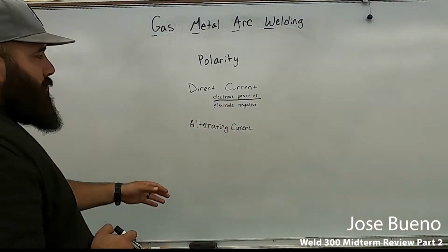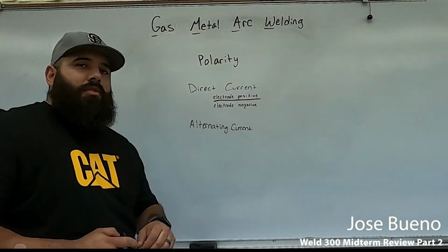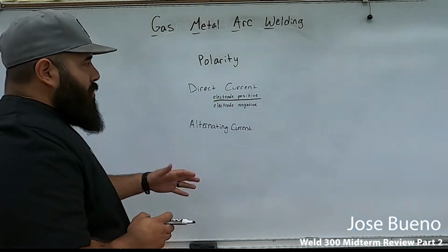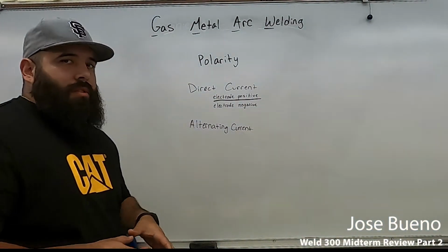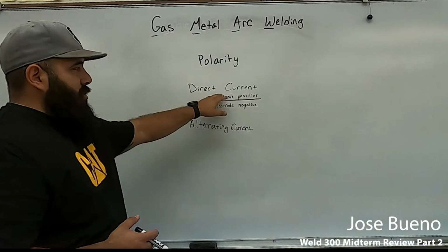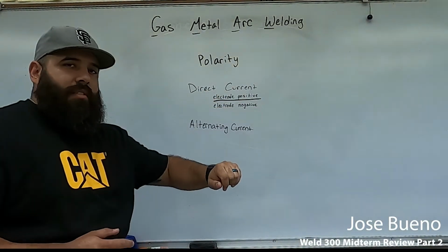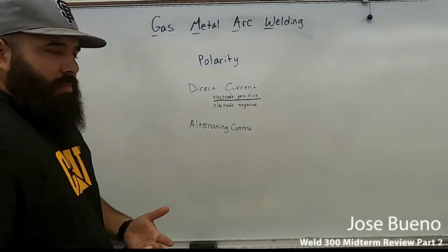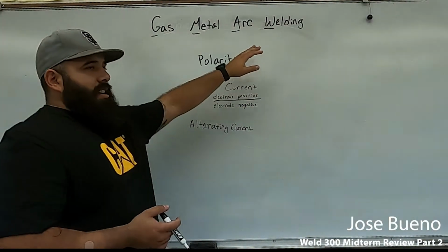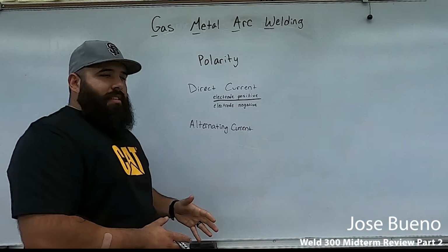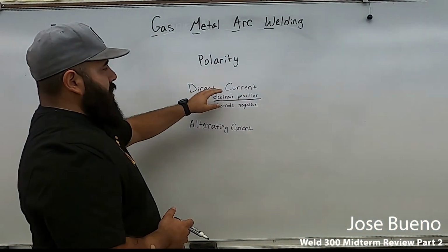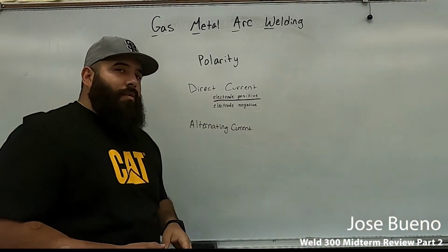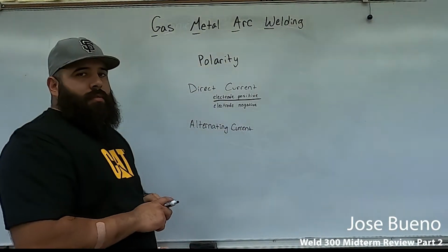Now there are times where you could be using alternating current, but in our course, we are sticking to direct current electrode positive. So for all intents and purposes, if you see a question pop up regarding GMAW, just think back to this. We are using direct current electrode positive for everything we're doing in this course.